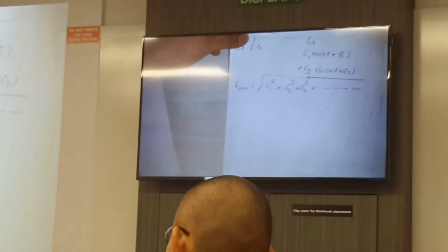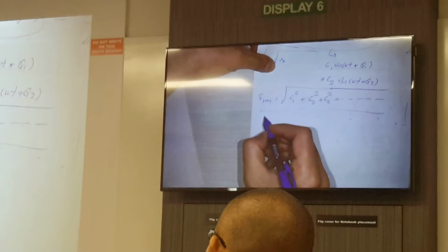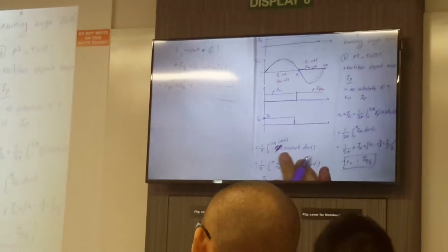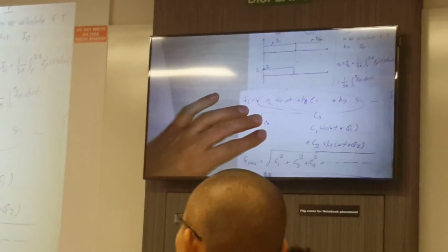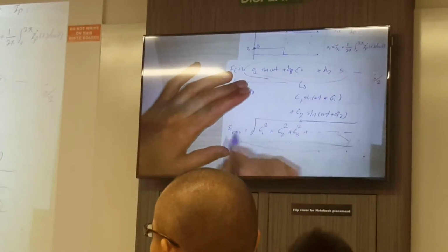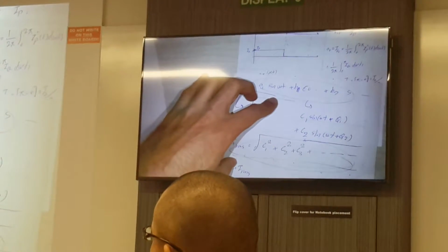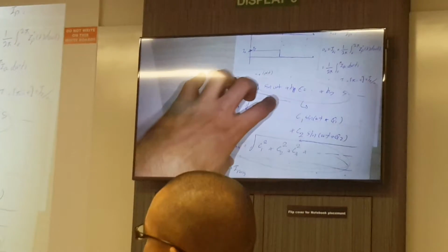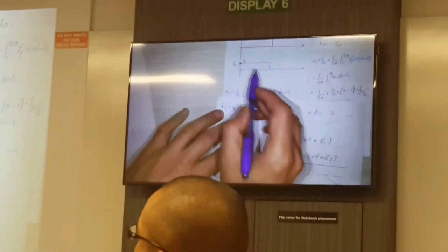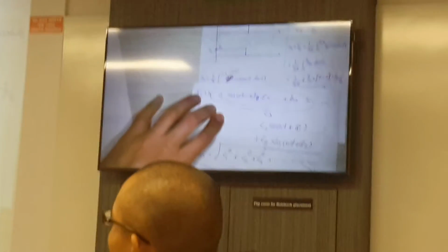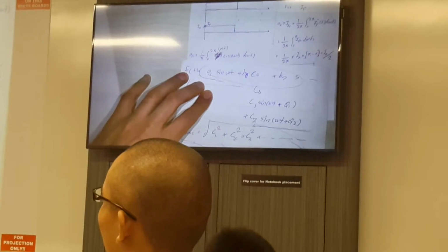But if you want to calculate all of these things, it will become more difficult. So another way is, instead of doing this, you calculate the IRMS from the signal itself. Because in most cases, if you calculate by this equation or calculate the RMS from the signal itself, the RMS value will be the same. So for us, it is easier to calculate the RMS value from the signal itself instead of using the Fourier transform.